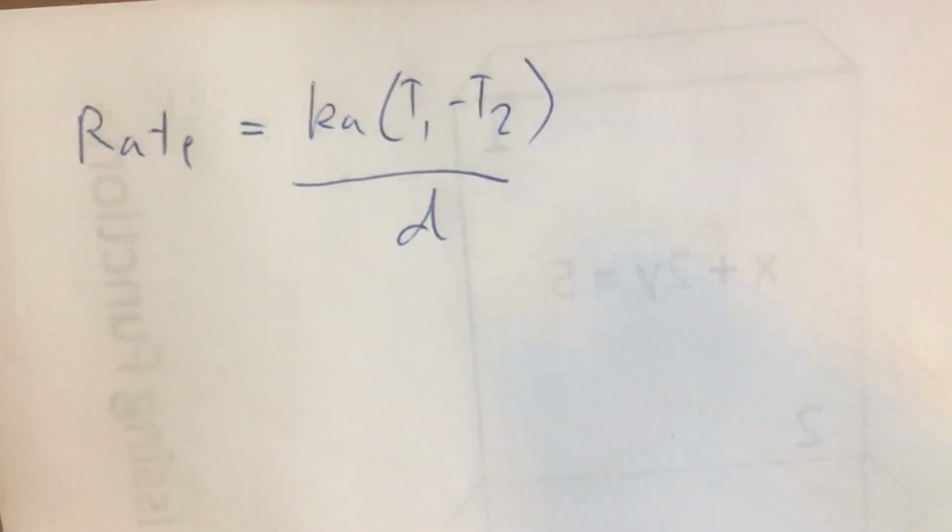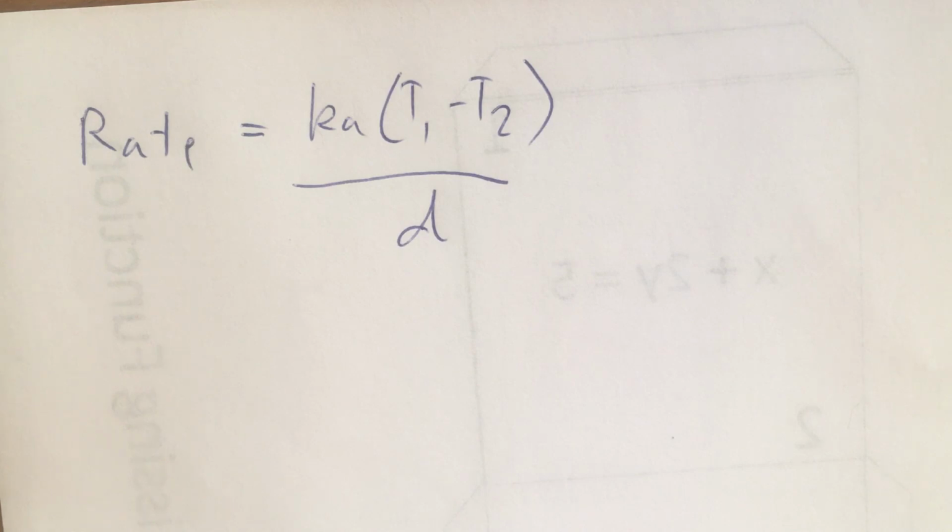So we're going to be using the same equation. And again, same deal, you might want to pause, write down the problem so that you can look at it while I go through this. But the problem says you have a styrofoam cooler with a total surface area of 0.54 meters with a wall thickness of 5 centimeters and a thermal conductivity value of 0.03. You have ice inside the cooler, keeping it at a temperature of 0 degrees Celsius. If the temperature outside is 30 degrees Celsius, what will the rate of heat transfer be out of your cooler?